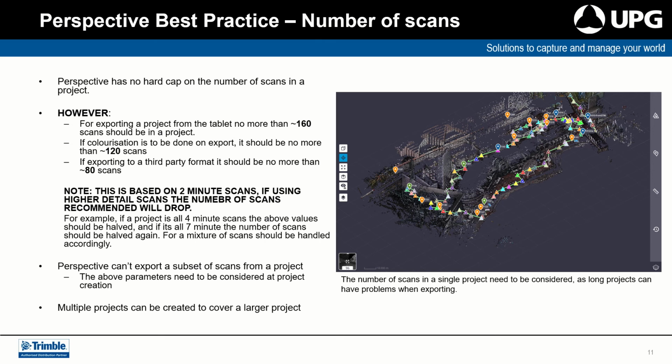Maybe it's better to create a different scan project for different floors of a building, for example, rather than having one single scan project for all floors. When looking at Trimble Perspective in particular, it's recommended that no more than 160 scans are in a single project. Any more than that, the tablet does not necessarily achieve its full capability, and you may have difficulty getting that